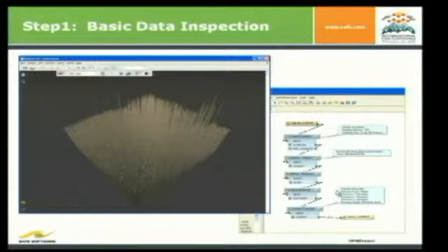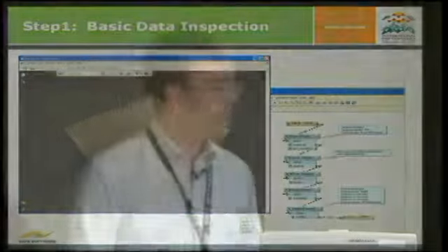This is actually the stage where you are just getting to know the input data. There's just the text file in here, and then we have some expression evaluated to exaggerate the elevation of each point. We create a 3D point, and we also make some kind of extrusion here to make this data easier to look at. If you extrude it, it's easier to see the surface in the laser scan data instead of just plotting the 3D points by themselves, so you can turn them around.